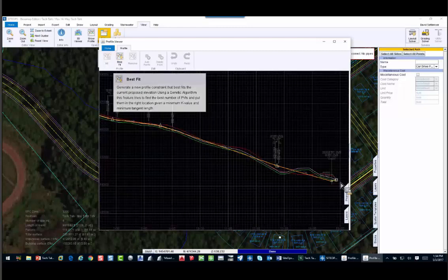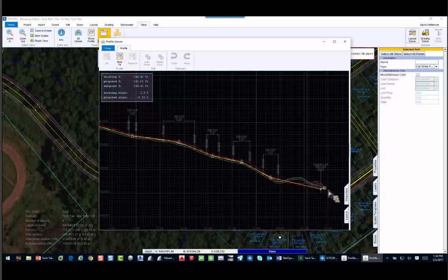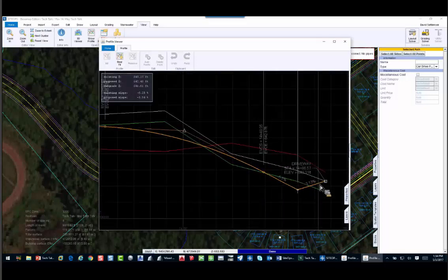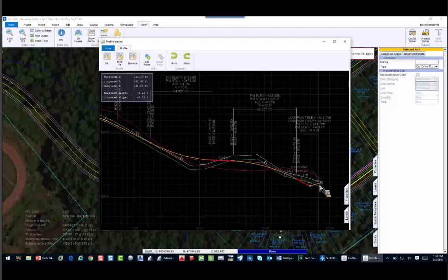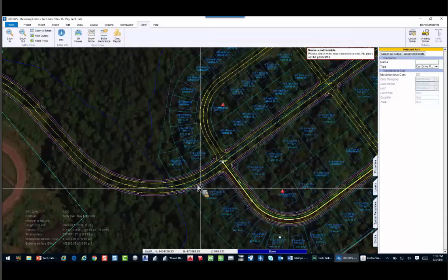And if you look, when it gets done, on the ends, it's going to lock this into place. Because these endpoints, as you can see the cross section of the other road, I've told the cross section of that road to be 3.13%, and it held that in. Now we're going to be able to go in, and let's just close this for a second, and I want to reopen them back up.